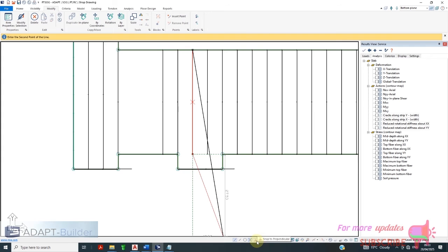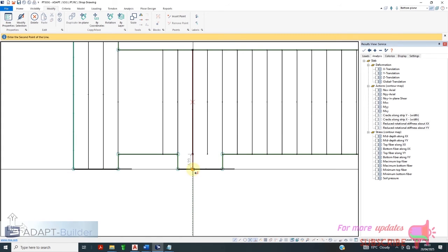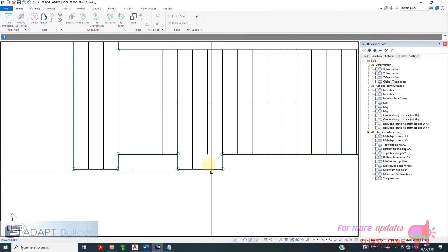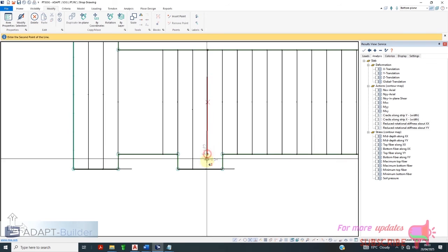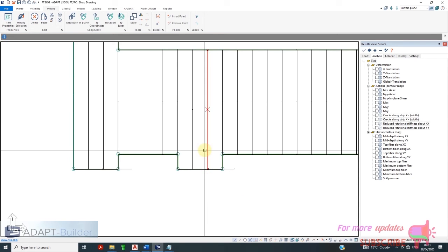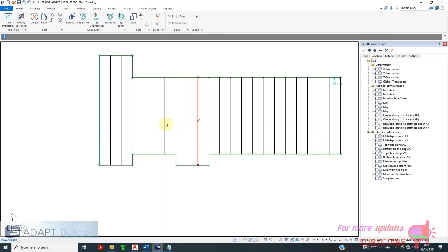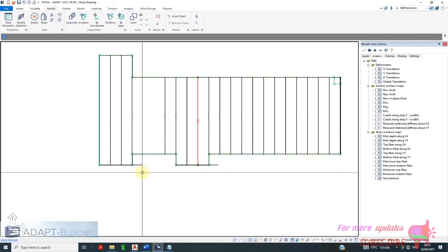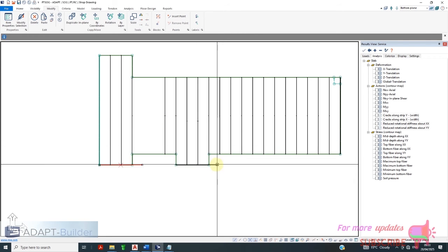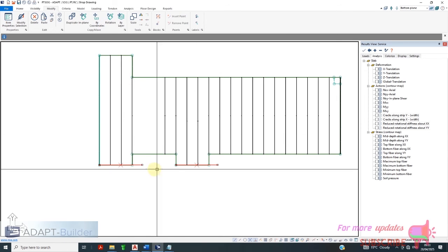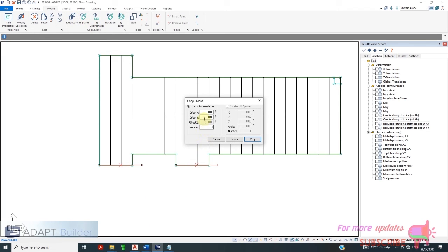Okay, I want to snap there, perpendicular. You can use the snap to assist you. And then this one I can just copy, select holding control, and then copy just one by coordinate in the Y, 5, just one of them, copy.